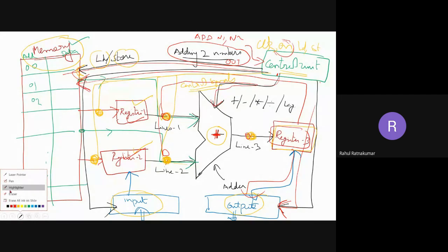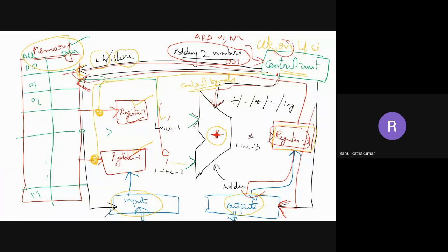So basically, I want to tell one more thing. The control unit is functioning based on a lot of switches. Instead of these lines I'm showing you, this is actually done by a lot of switches. That means the control unit is controlling this by simple switches. This is S1. Now this another switch S2. Now output switch is S3. Right. So the control unit is just turning on and off these switches. And there are some switches in the load area. This is the load switch, and if it is zero, the store switch, and a lot of switches, and these switches are transistors, nothing but MOSFETs or BJTs, usually MOSFETs.